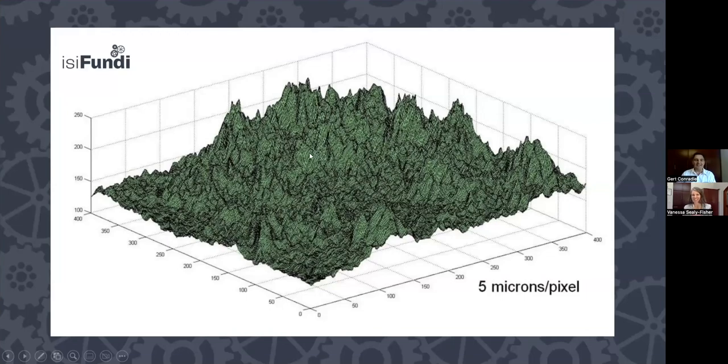It almost does, because what we have now done is roughen the surface, and quite rightly, as you have described, you can see these peaks and you can see these valleys. So when we measure the profile, where are we measuring? What's the representation? Just like when we spoke about it earlier, you cannot take a single measurement and say, look, now I can pass or fail this area for being rough enough or clean enough or thick enough or whatever it might be. You have to get a representation of an entire area.